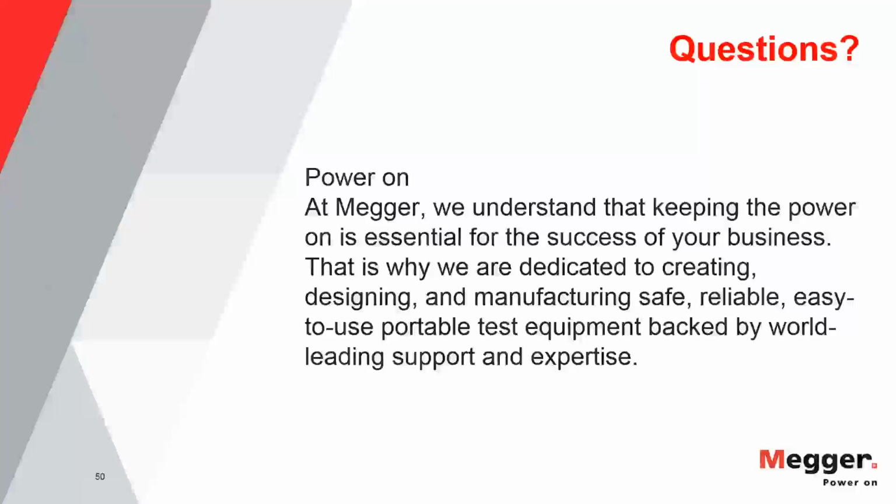So, the basic idea of this is that for extruded cables, XLPE and EPR, it should be PD free up to twice rated voltage. There should be no detectable PD. That criteria isn't really practical for aged cables. You're going to eventually have some PD, but the criteria then for aged cables on extruded cables is for the insulation itself, not splice, not termination, but the actual insulation, that should be very much PD free at rated voltage. For joints and terminations, there's a lot more material there, so they're able to tolerate a little bit more partial discharge before they actually fail.